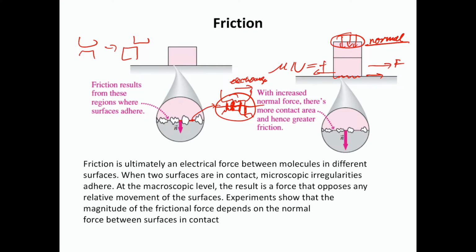What we want to do is find out what friction depends on and what it does not depend on. You might be surprised. First, I have 4 blocks, all about the same size and the same weight. With a spring balance, I have found the weight of them. Each one is about 2 newtons. Now we're going to measure the friction pulling 1, and then 2 of them stacked, 3 of them stacked, and then 4 of them stacked. And then we will plot a graph of the friction versus the weight.